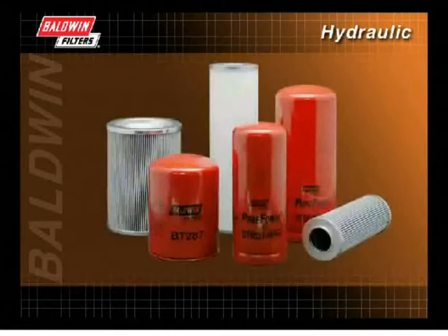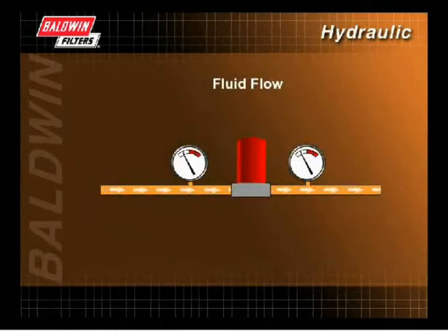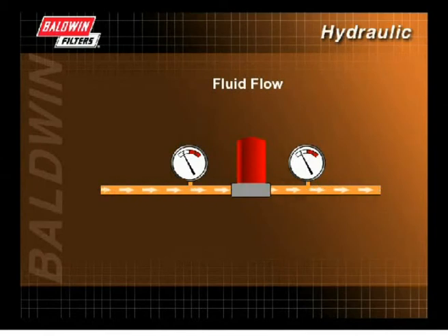The fluid flow in your system will also be a factor in determining the correct filter use. It is important to have the right size filter to meet your system's requirements. Because fluid can only travel through the filter media so fast, a system with a faster flow rate will need larger filters than a system with a slower flow rate.